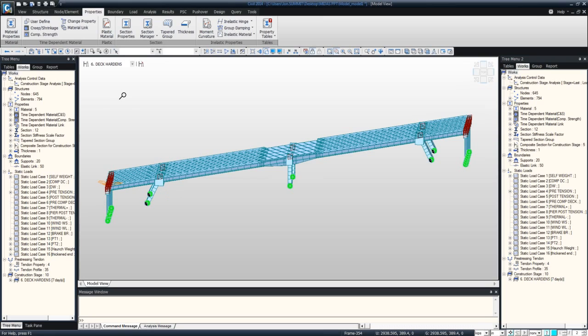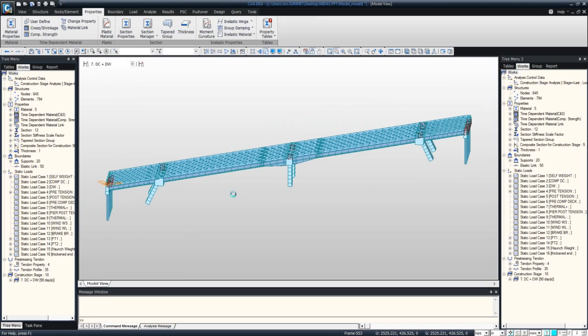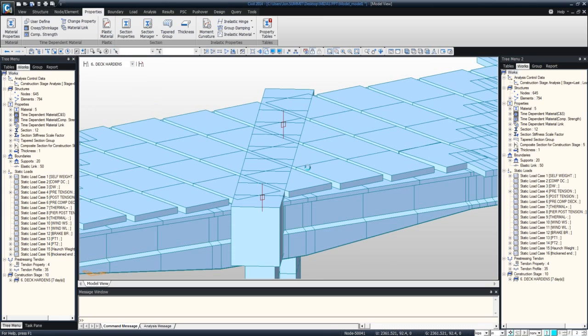Okay, now the deck is cured. One thing I will point out here, just to demonstrate the composite sections and when they can be activated, what I've done is activated everything but this haunched girder at the deck hardened stage. I've saved this haunched girder for the next stage. So if we go to the next stage, we can see then that is fully active. When we go back to this previous stage, it's a good example of what the grillage analysis looks like.